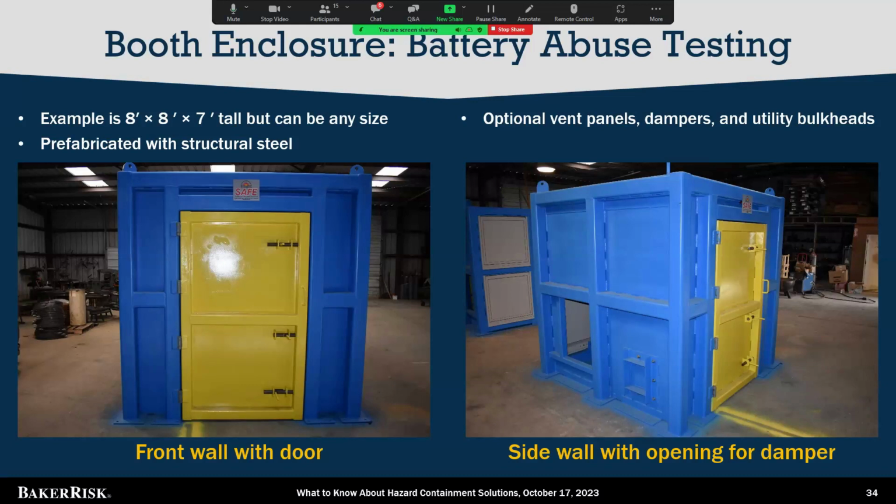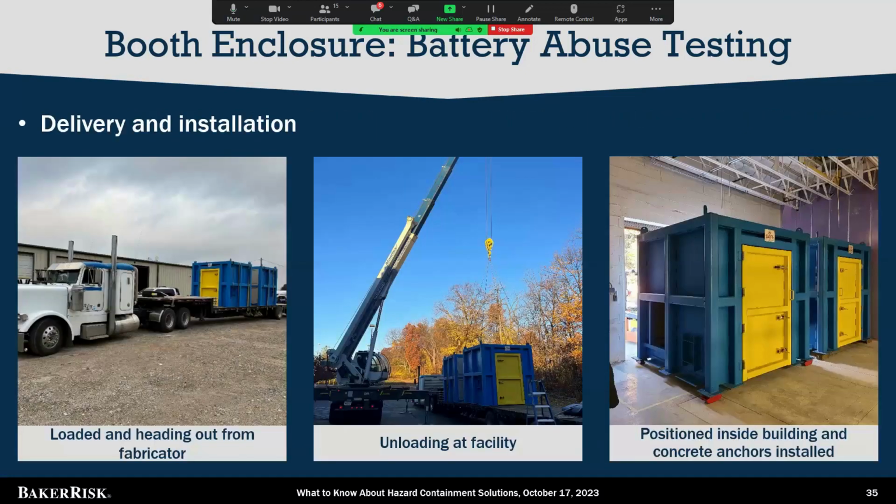These gray panels are vent panels. So this one was designed so in case of an explosion from battery abuse testing, the blast loads would vent out those panels, they open up, and the loads would go outside.